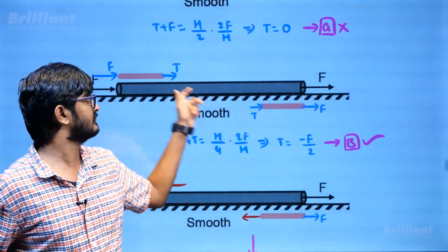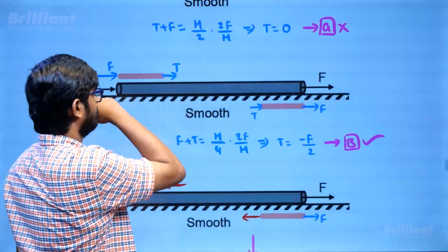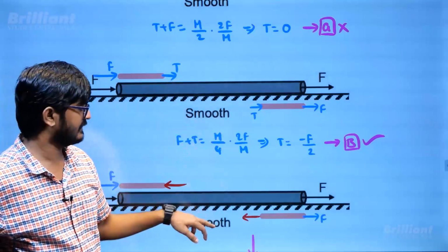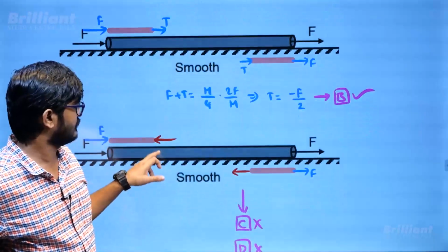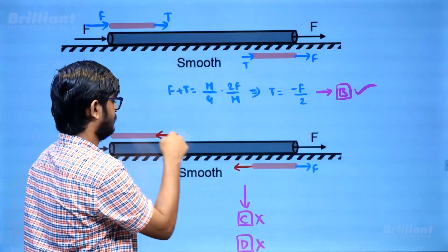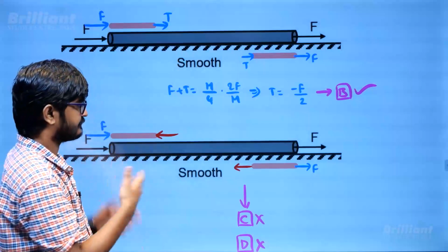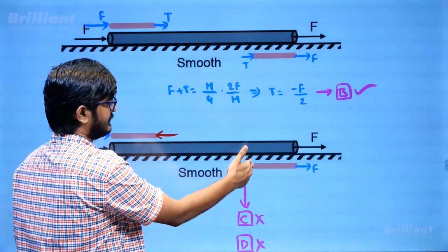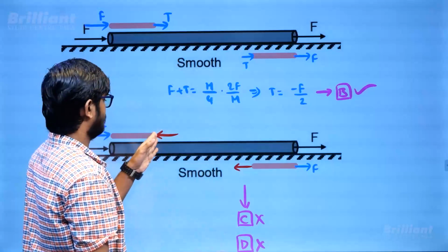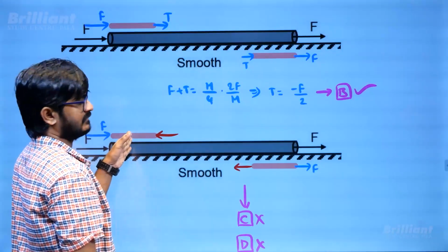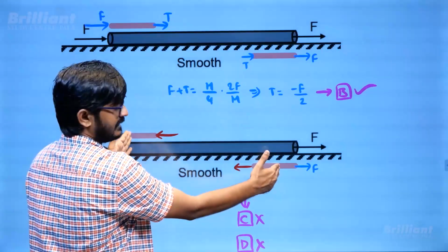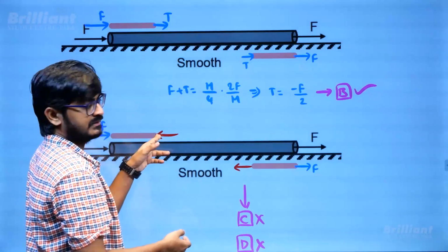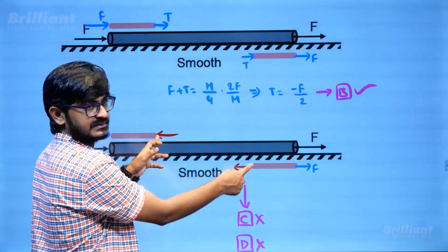This force is going to be this way, this force is going to be this. So this is going to be compressive, this is going to be tensile. So when I put it in the right figure, this figure looks like this when I put it correctly. F by 2, F by 2. Now you can see the same thing is going to happen again. So this tensile force is equal to this compressive force. Now here compressive force will be equal to here tensile force, right? So you can see whatever compression is happening at this point, it will be balanced by this extension.